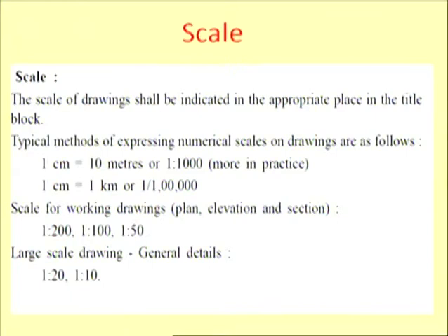So if the area is very large, like a map of a large area or the layout of a large township, in that case you may have a larger scale, that is 1 centimeter equal to 1 kilometer, or 1 centimeter equal to 10 kilometers, depending upon the size of the land area which we are going to develop, and the size of the sheet available with us.